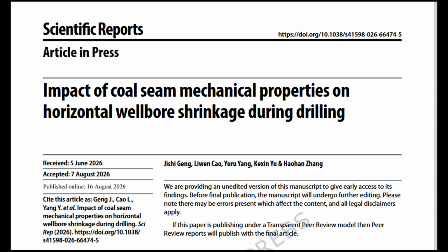Equation 11 is the continuity condition at the interface between the plastic and elastic zones. It requires that the sum of the radial and tangential stresses at that interface equals twice the far-field stress. This ensures a smooth transition of stress across the boundary. Equation 12 then uses the yield criterion together with the continuity condition to determine the radial stress exactly at the elastic-plastic interface. This value depends only on the far-field stress, the friction angle, and the cohesion, not on the wellbore pressure or the hole radius.